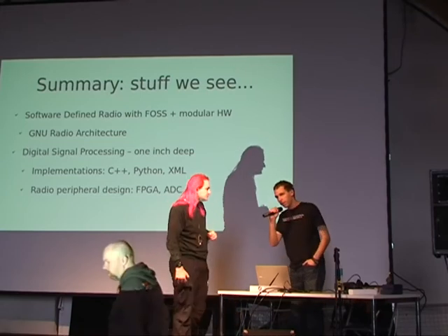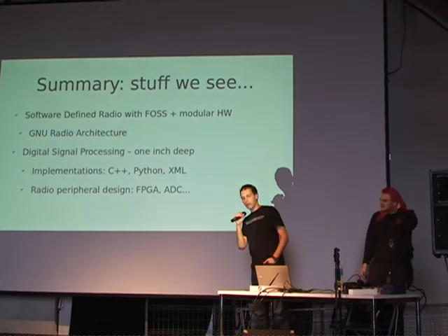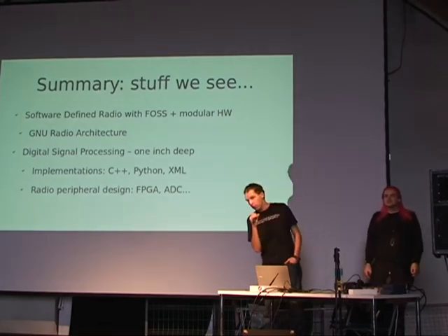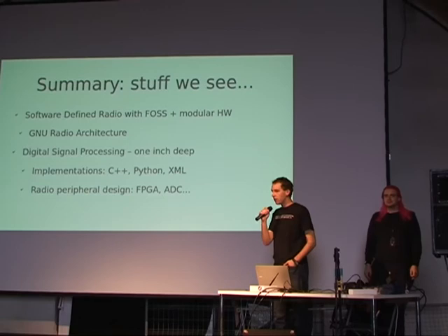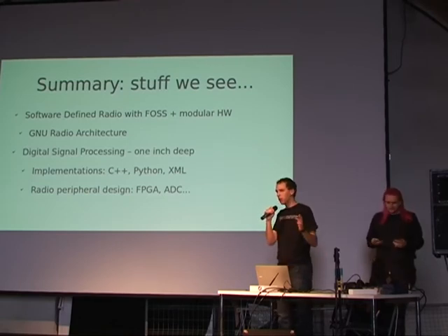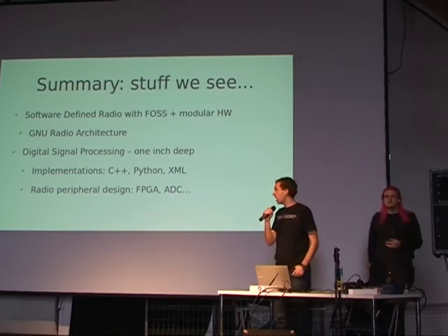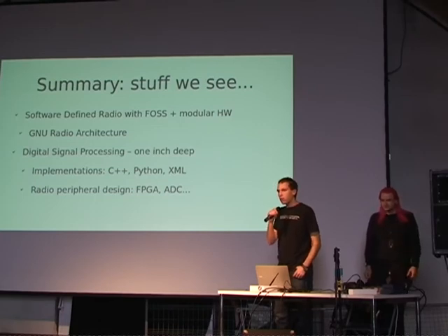All right, now I understood the question. You can, of course, bundle a set of USRPs to cover the whole frequency range. There are device drivers that work IP-based. You can have 25 megahertz with the USRP2, and there are newer devices that can cover the whole ISM spectrum. For scanning, there is spectrum sensing.